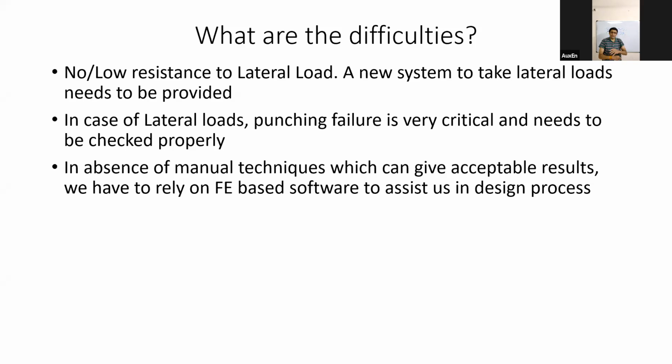Even if you have provided proper shear walls and properly made it earthquake resistant, still in case of earthquake loads, lateral loads, your punching effects become even more critical for us. So you have to take care of punching even more. That entire thing becomes even more critical for us to design.